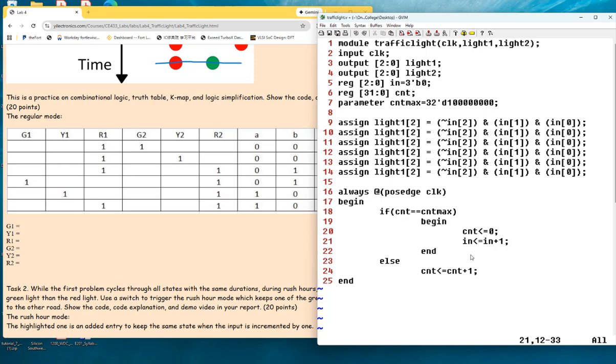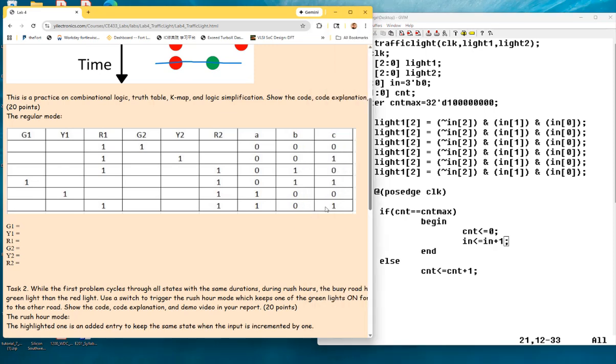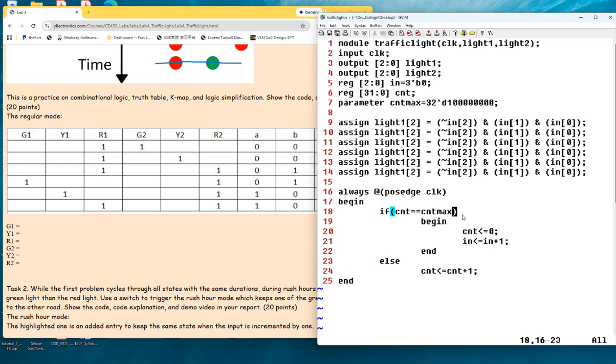Or is this the right way to do it? You only have 6 states, right? It only counts up to 5, and the 6 and 7 don't have any corresponding outputs. So you want it to wrap around when you hit 5? Yeah, wrap around at 5. So what else do you need over here?